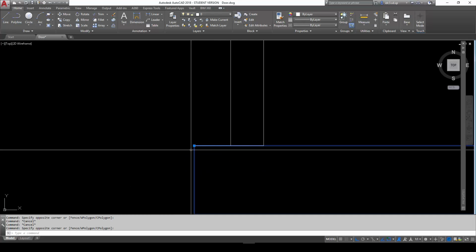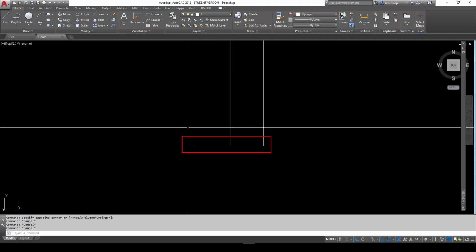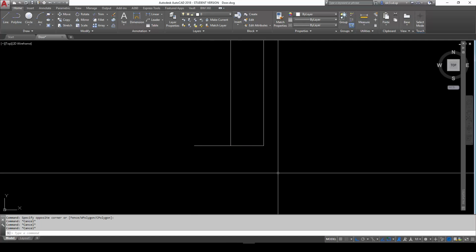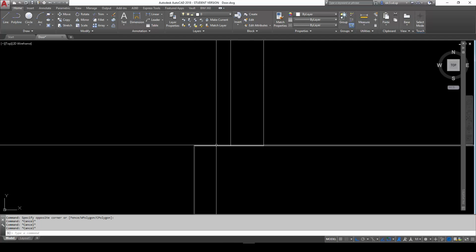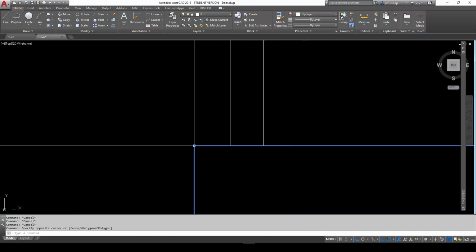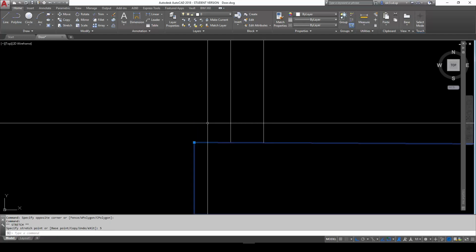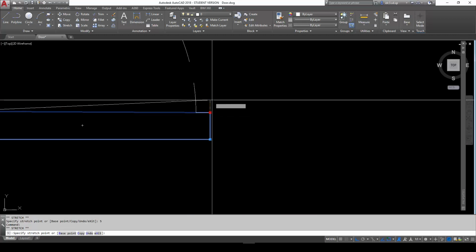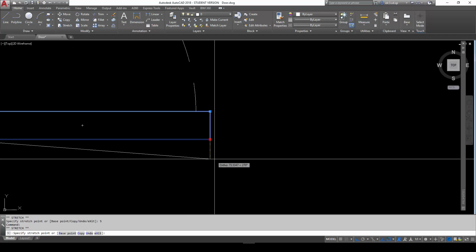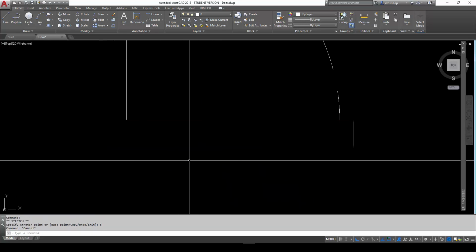If not, there will be some interference here because the coordinates all land at the same location, and AutoCAD has difficulty identifying what we want to show and what we want to hide. So we are going to move this higher by 5 mm, and the same thing, move this up by 5 mm also, this way. Down by 5 mm, down by 5 mm as well.